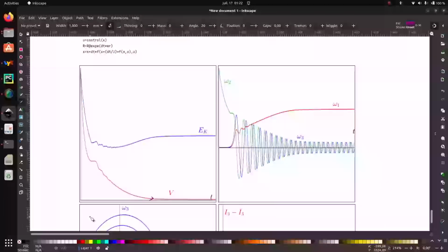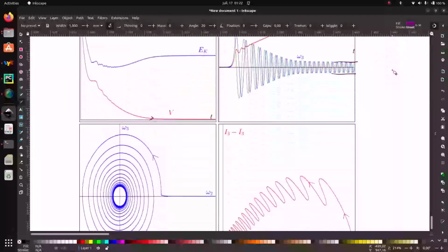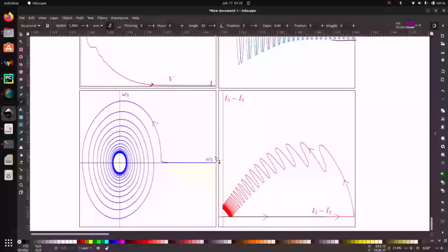And if I see the vector omega r, which is omega 1, omega 2, omega 3, at the beginning I see that I was rotating along the second axis, so omega 2 was equal to 10. And then after it decreased slowly, but here I do not converge to 0. Okay, and omega 1 is increasing, which means that I am more and more rotating along the first axis, which was exactly what I wanted. So if I see in the plane omega 2, omega 3, I can see that I started from here, I was turning along the second axis, I moved like this, and slowly I converge to some kind of cycle, but I do not converge to 0, which is what I wanted.